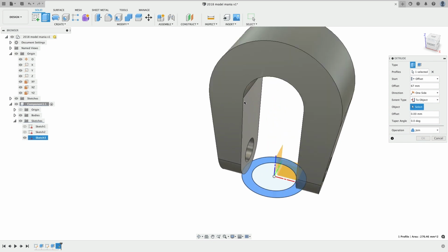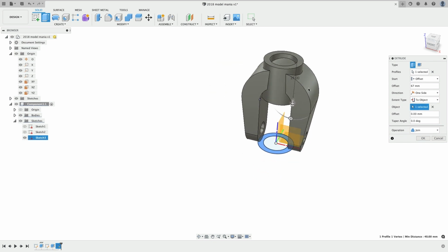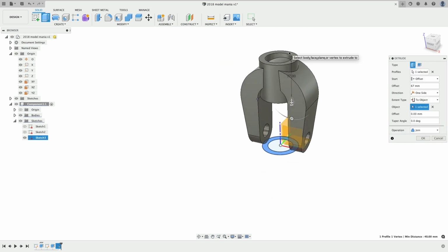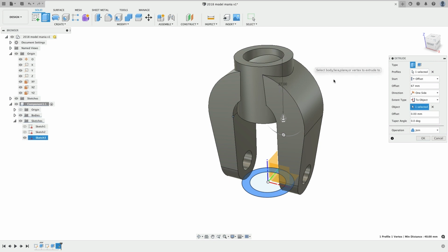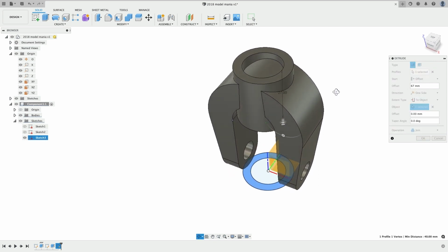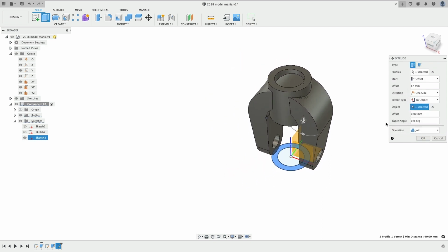So which object am I coming down to? Let's try this point, and extruding, starting up high, coming down to a point. Pretty cool. Now, could you have just put a plane up in space? Absolutely, that'd work great, but just a good thing to be aware of that you can change where things start and where they end in the Extrude tool.